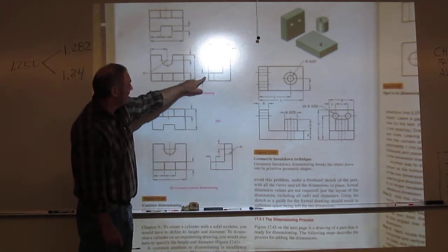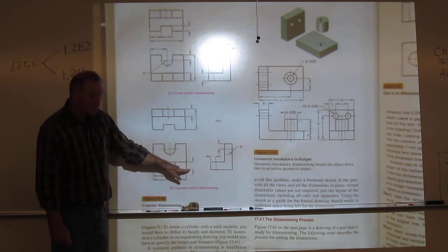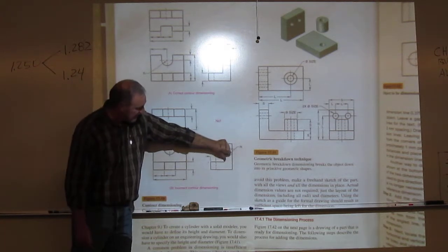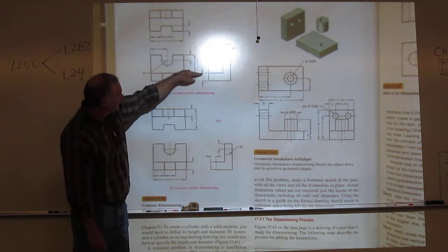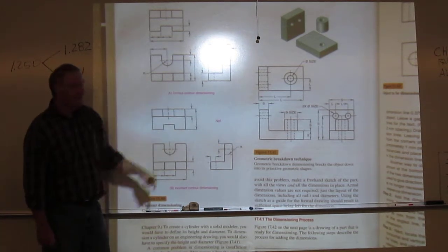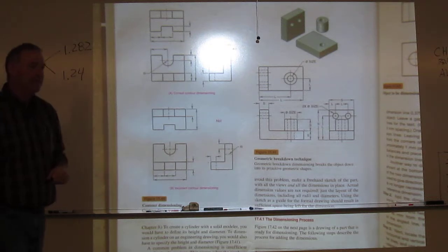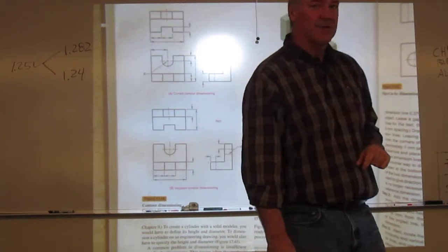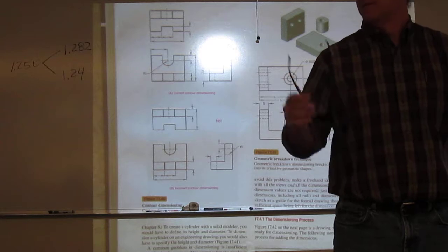The height here is a great example. You'll see this a lot where people have dimensioned that height right there. Well, we've got an interior to the object. This is a much better look at the height of what that bottom plate is. So therefore the dimension should be sitting right here. You kind of get an idea of that? So contour dimensioning is putting the dimension in your best look at the feature. This should be the first thing you do with everything, and it kind of overrides all of them.